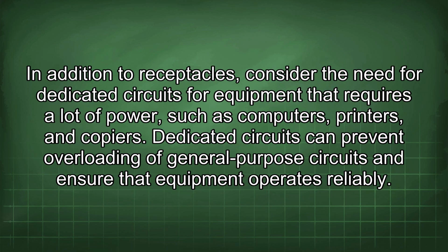In addition to receptacles, consider the need for dedicated circuits for equipment that requires a lot of power, such as computers, printers, and copiers. Dedicated circuits can prevent overloading of general-purpose circuits and ensure that equipment operates reliably.